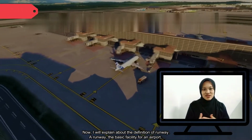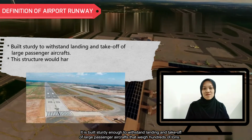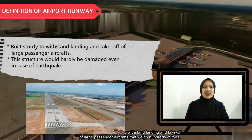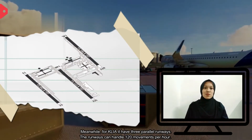Now I will explain about the definition of runway. A runway is the basic facility for an airport. It is built sturdy enough to withstand landing and takeoff of large passenger aircraft that weigh hundreds of tons. Meanwhile, for KLIA, it has 3 parallel runways. The runways can handle 120 movements per hour.